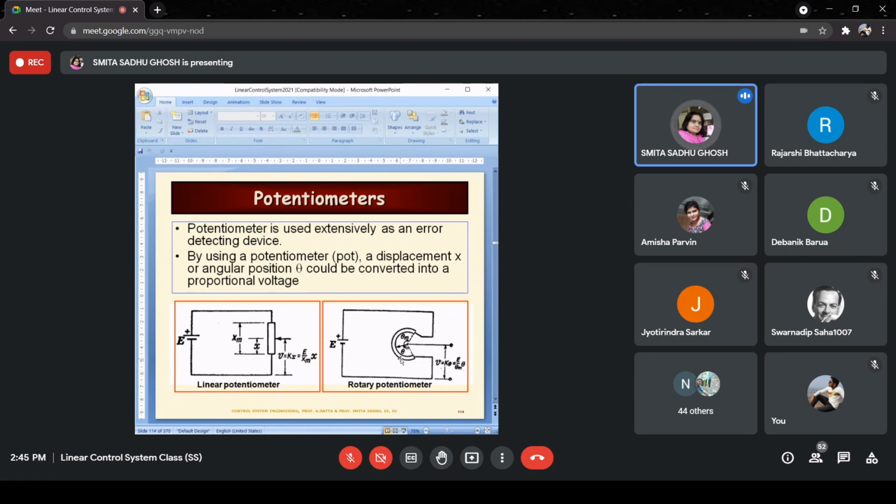And now, depending on the angular displacement theta, we will get an output voltage V. So V is going to be proportional to the angular displacement theta from this end, where theta suffix small m is the maximum angular displacement, which can be indicated by using this rotary potentiometer, right? So small v is equal to some constant into theta, and that constant will be equal to how much? It's going to be capital E by theta m, because theta m is the maximum angular displacement which we can have, and E is the source of EMF. So basically, V is equal to E by theta m into theta.